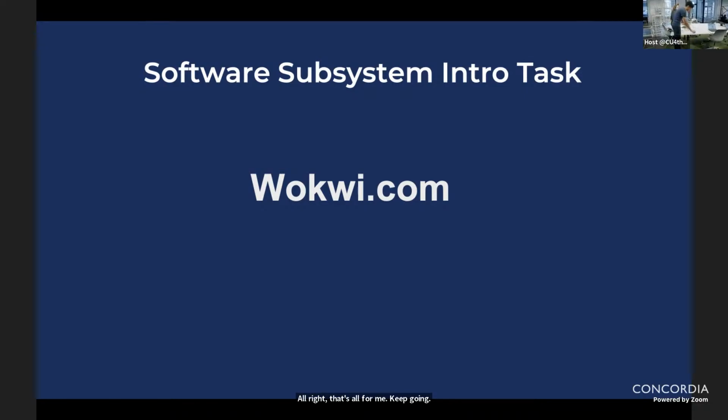Okay, so there's a lot of electricity involved with embedded programming. So you deal with software, hardware, and you also deal with connecting wires. So step one, the most important thing with embedded programming: never connect your wires to the boards while they're plugged into the computer or while they're plugged into a power source, like a power supply. Make sure you set up the wires correctly before you ever plug in power, because you risk frying the board when some things aren't connected before the others, okay?